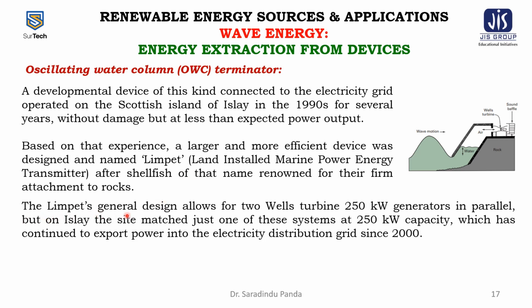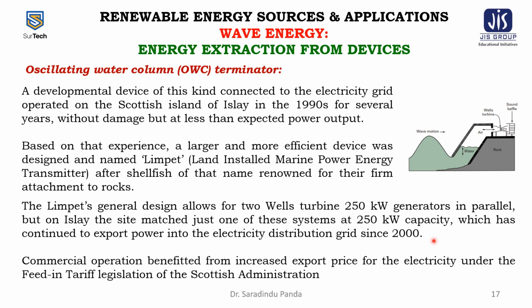The Limpet's general design allows for two Wells turbine 250 kilowatt generators in parallel, but on Islay the site matched just one of these systems at 250 kilowatt capacity, which has continued to export power into the electricity distribution grid since 2000. Commercial operation benefited from an increased export price for the electricity under the feed-in tariff legislation of the Scottish administration.